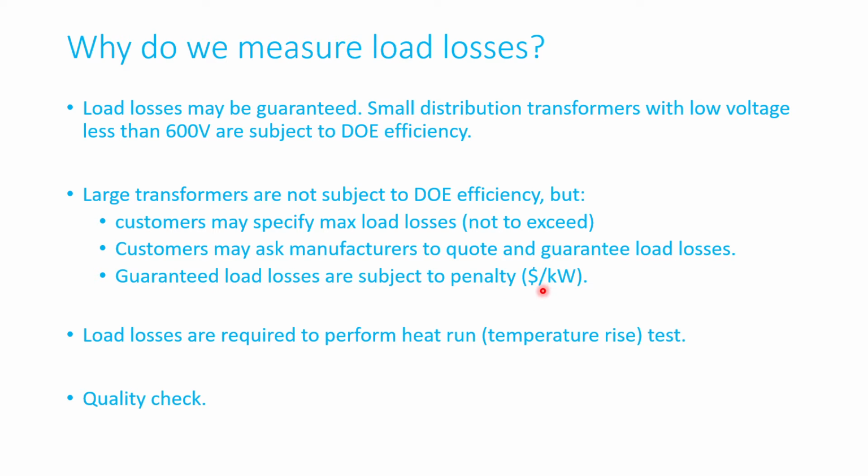So typically, it's dollars per kilowatt above the guaranteed load losses. Load losses are required to perform the heat run or temperature rise test, to determine what the temperature would be when the transformer is subject to the rated load.